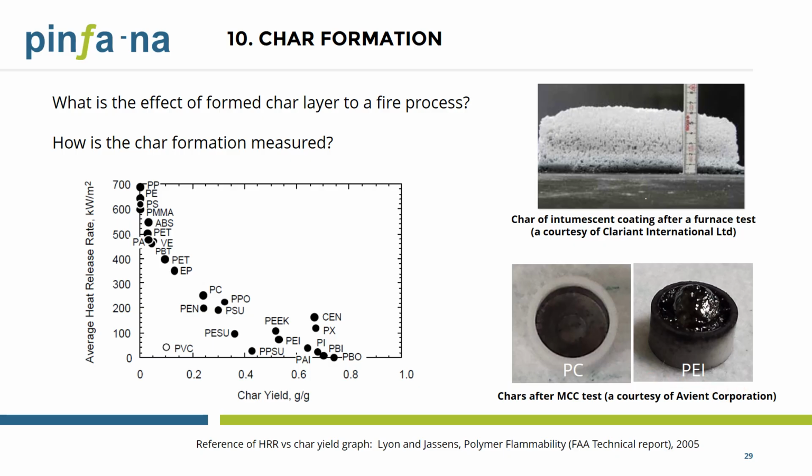the photo here. In the cone calorimeter, horizontal burn, or furnace exposure test, the char formed at the end of the test can also be evaluated quantitatively or qualitatively. First, the weight of the char can be calculated based on the mass loss result and the non-inorganic filler content of the formulation. Secondly, the height or thickness of the char layer could be measured if intumescent samples are tested. An example is shown in the photo on the upper right here.